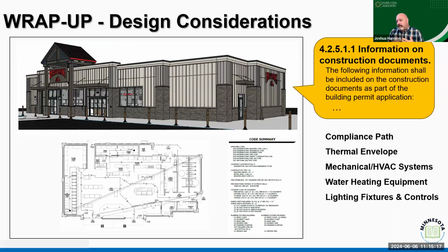So I know we've got about 15 minutes left, and hopefully somebody's got some questions. But one of the things I think, wrapping up, is that the critical concept when we think about overall high-level design considerations for building projects is always to identify what the compliance path is, because that compliance path is going to drive for us all of the other elements as far as our expectations when it comes into the plan review process.